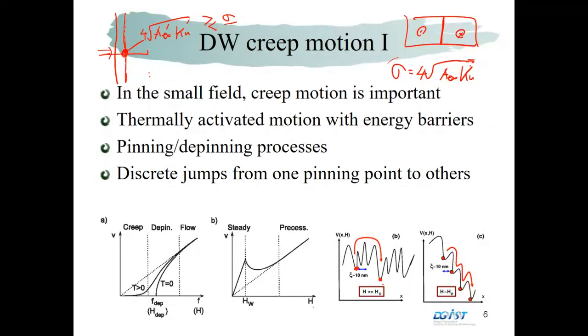In this one-dimensional plot, we have a large domain wall energy region here. If the domain wall is moving in this direction, there's no energy difference, so it can move very easily. But when it meets this energy barrier, if the domain wall touches this area, that means we increase the system energy because of the large domain wall energy. So it starts to bend, something like this. That's what we call pinning. Then the domain wall length is increased compared to here.